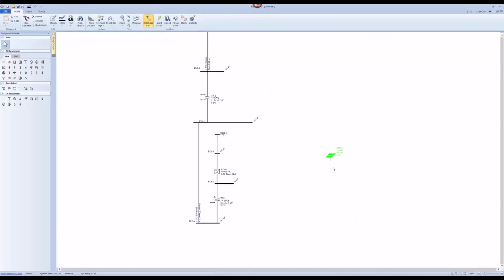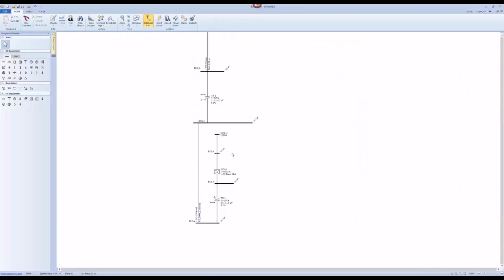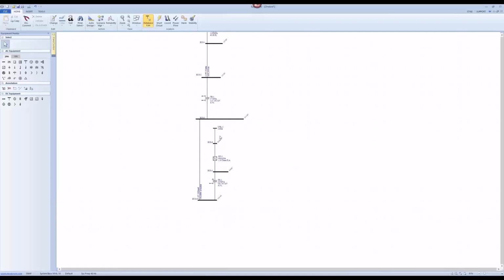We don't want to focus on that today because there is a lot of calculation involved. Or just use a DC utility source to represent it, because at the end of the day, you only want to study the interface from the AC output of your inverter, together with the utility. You don't really care too much about how your DC side works when you study harmonics, because there is no harmonics in DC. Every input is an inverter, right?